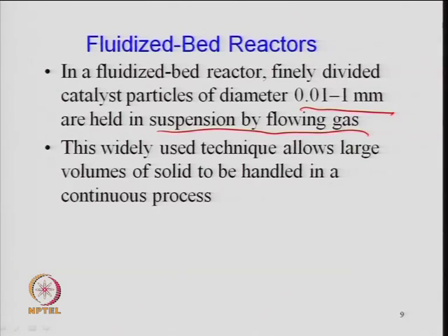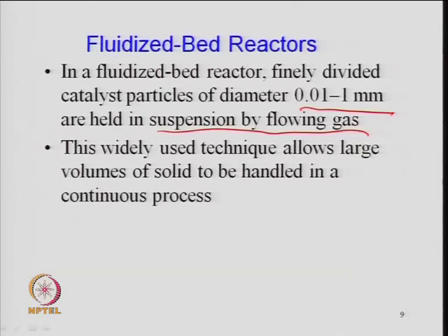Generally, say nitrogen can be the gas, and you pass it through sand and increase the velocity of the nitrogen gas. At the end you will find that the particles are floating in that column. Initially it is a fixed bed, but the voidage between the particles increases, and finally the bed will start fluidizing. But if you keep on increasing the velocity, these particles will go away from the bed, which is not desired. So, this fluidized bed reactor technique is widely used in the chemical process industry,